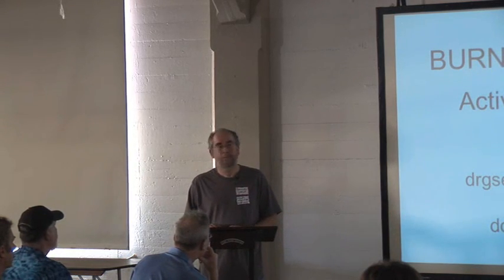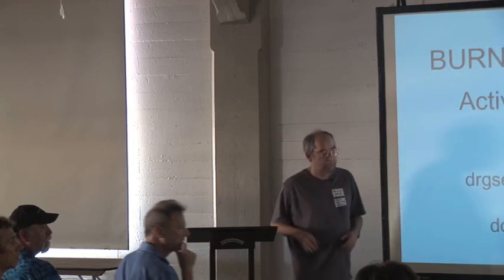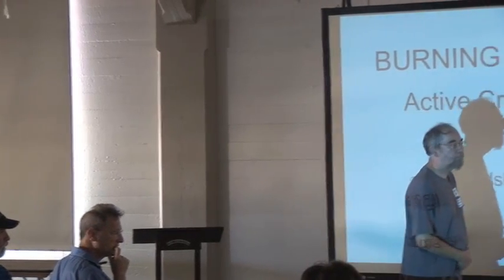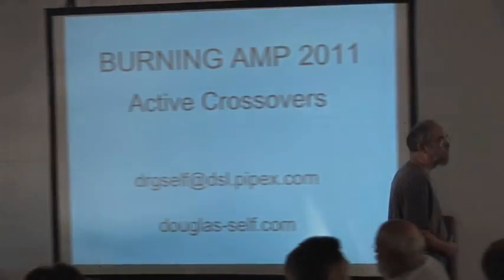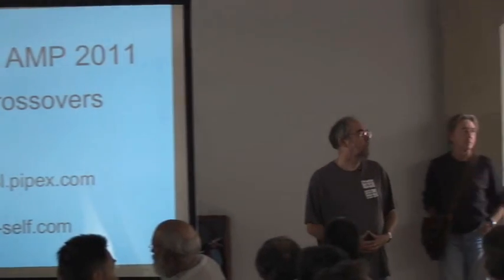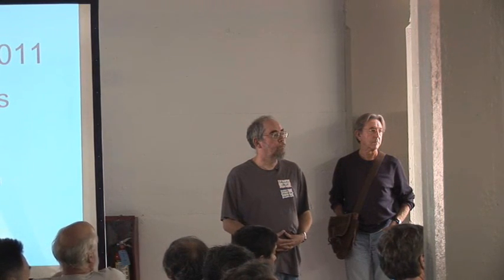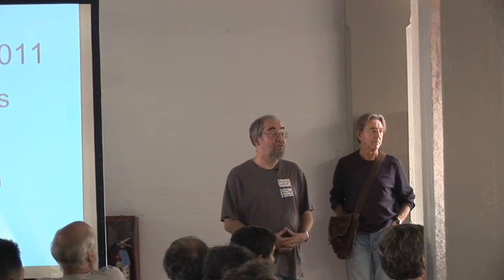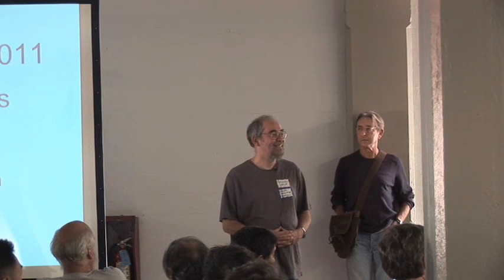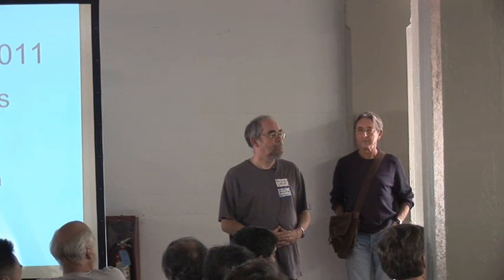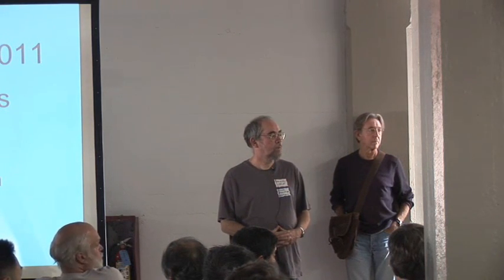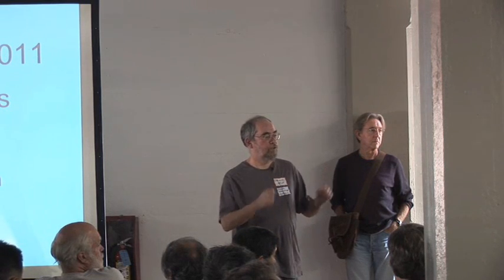Any more? Yeah, you were saying about having DC offset problems in power amps in tri-amp systems. And for tweeters, it's not so bad to get a reasonable capacitor. It's 50 microfarads of polypropylene, not so bad. Yeah, and expensive. Mid-range, expensive. Yeah, some of us have a little bit of money. But the problem is that if you want to do it with mid-range, then you start getting to hundreds of microfarads.